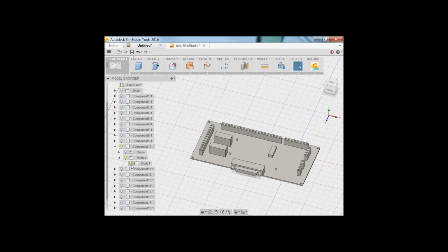So we've got these little small parts that look like an LED or a resistor of some sort. We actually have materials in CFD that can do the math for that as a simple block. Rounded surfaces are hard to mesh. So when I have something small like that, I really want to be able to make that into just a small cuboid volume.